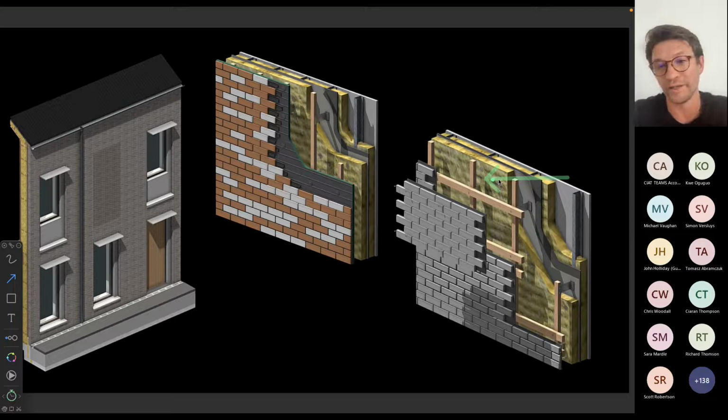So for low-rise buildings, brick slips could be considered, could be a good option to save on the thickness to thermal performance ratio if there's an opportunity to use high performance insulation, not necessarily mineral wool, but PIR or PUR insulation for more lightweight elements, and with the timber subframe. That's also worth considering for systems that are not necessarily non-combustible.